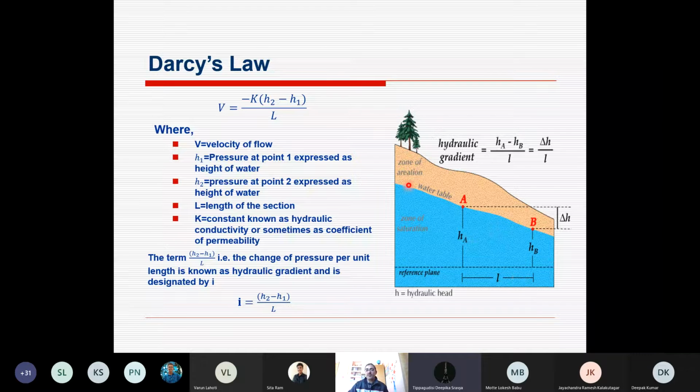You can take reference point either ground surface or groundwater table to find out the flow of water from these two places, from say upstream side of basin to downstream side of basin. We need to find out what is the hydraulic head there. It is now the matter of head, which forces water to move in a particular direction.